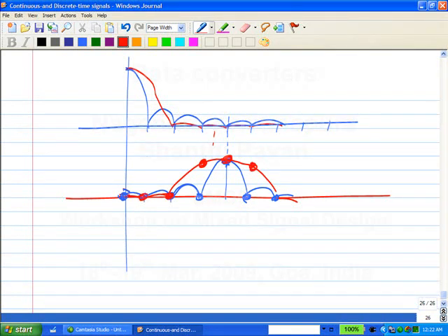Okay. So in fact, if you have a single sinusoid placed on one of the bins, as these are known, placed on the frequency k by n, you will get 3 non-zero points, whereas you will get only 1 non-zero point with the rectangular window. So that non-ideality is there. Even when it is accurately placed, you still get 3 points. But what does it mean? That means that if you had one sinusoid here and another sinusoid here, you certainly cannot distinguish it with the Hann window. But if you have one here and another smaller one here, you can do a much better job with the Hann window than with the rectangular window. Okay? So it trades off. This is known as the main lobe size. The main lobe gets broader, but far away it is not interfering.